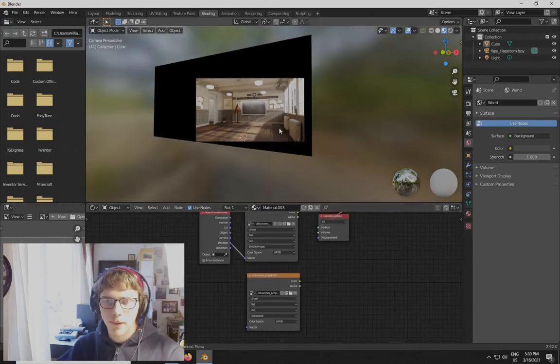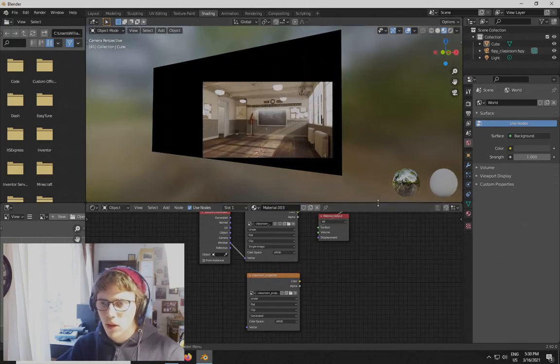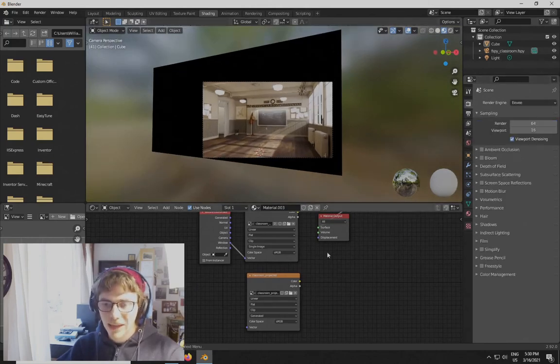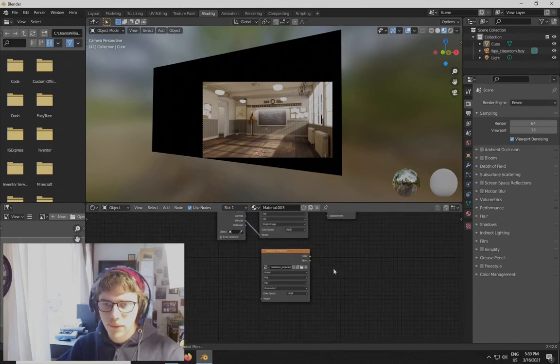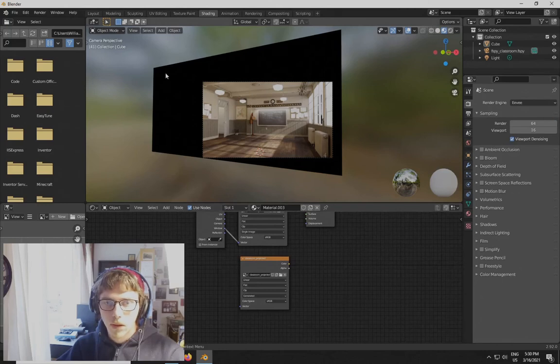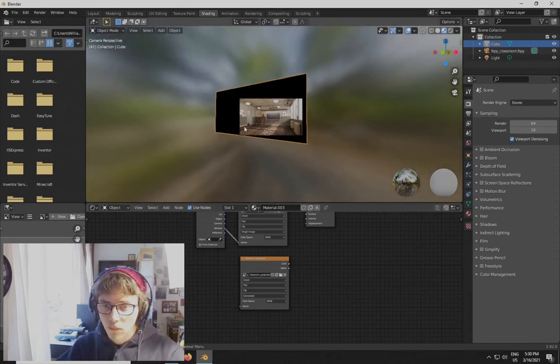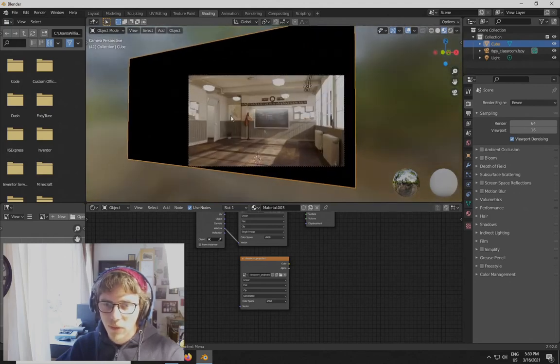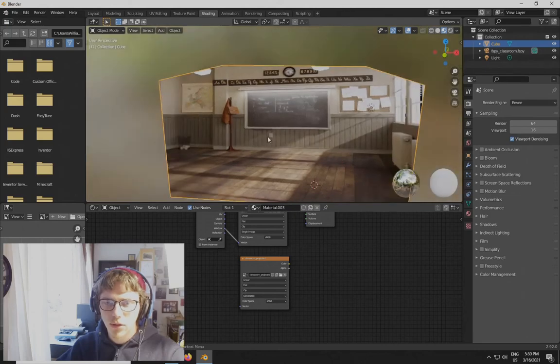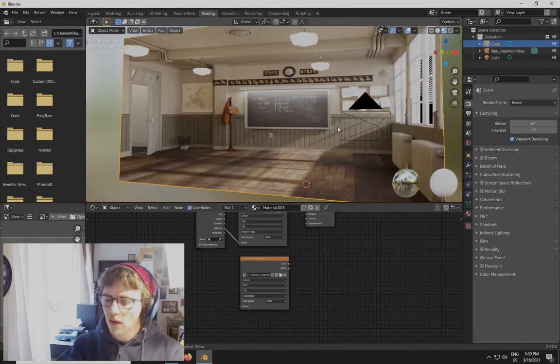Blender has this feature that makes what I'm talking about possible with Cycles called baking. Specifically baking in the context of generating the entire texture all over this object and then saving it as a single image based on its UV map, so you won't have to calculate it later. The reason that's useful to us is that calculating it later, when the camera's in a different position, let's move the camera. Oh, look, it's entirely not useful. So we want to calculate it once in this position and never calculate it again.